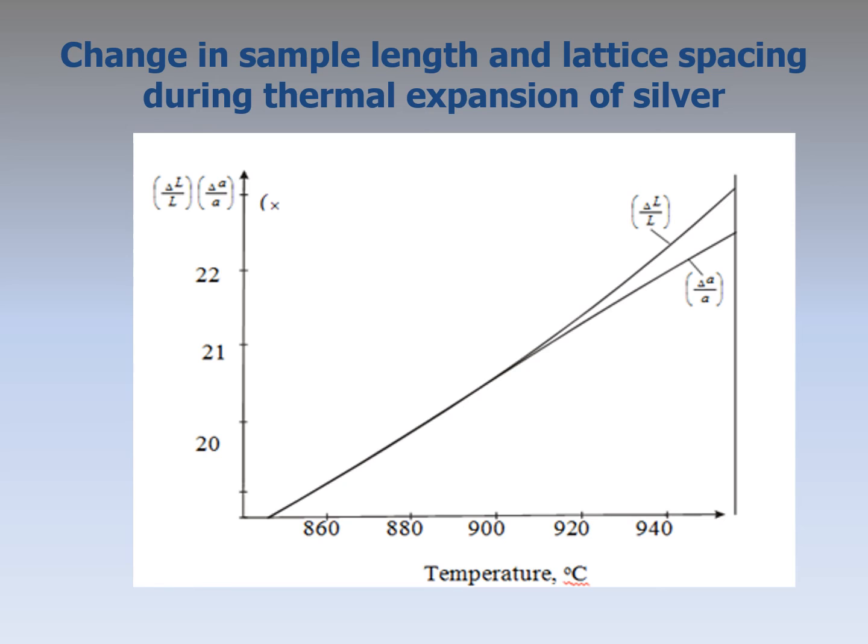Having plotted the graph of this quotient in the coordinates of electrical resistance and temperature, we obtain a straight line whose tangent of slope is equal to the energy of formation of a vacancy E. Then it is easy to calculate the equilibrium concentration and derive it, big N.